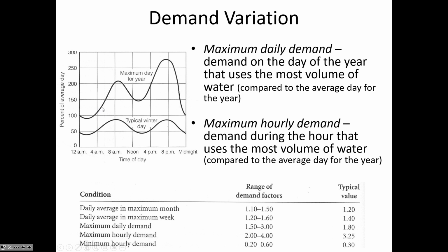And so here is an illustration of one typical temporal variation for water, a diurnal variation where there's a set of peaks in the morning and in the afternoon, corresponding to people waking up and using some water before they go to work, and then water demand being a bit lower during the day when people aren't doing things like washing clothes and dishes and watering lawns and cleaning cars and so on. And then in the evening is when the water use is its highest.